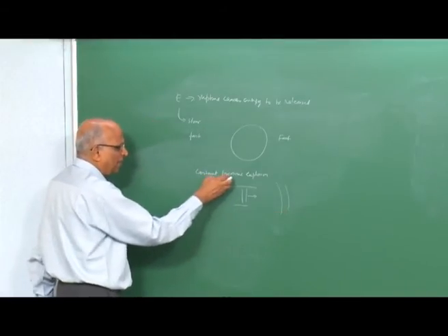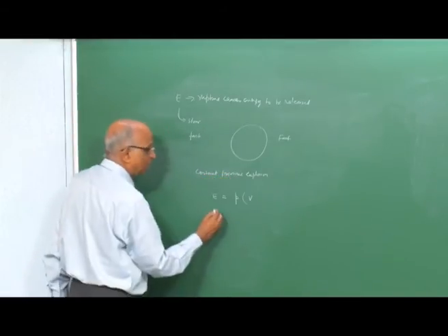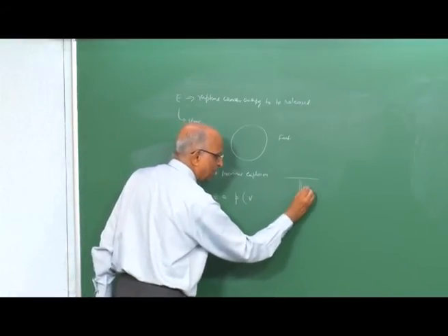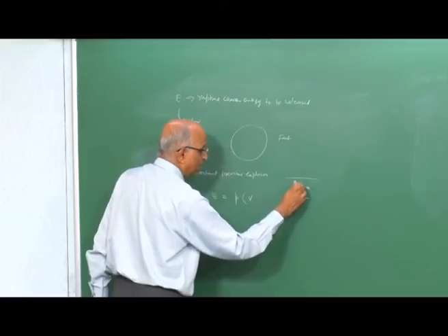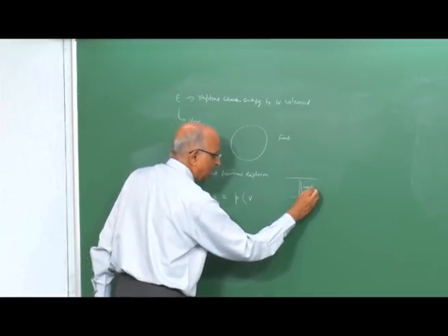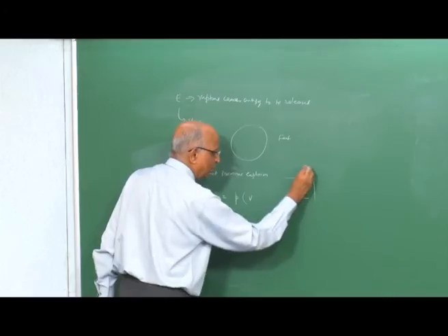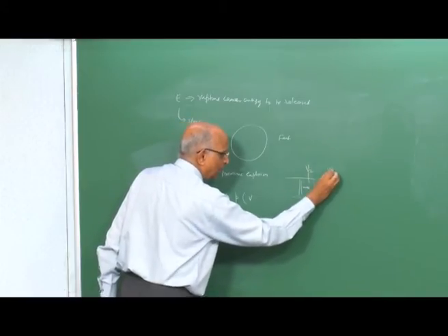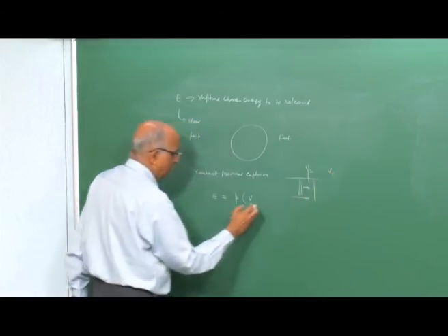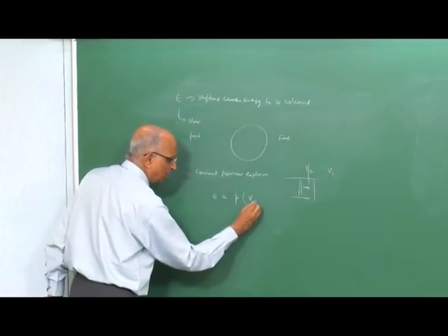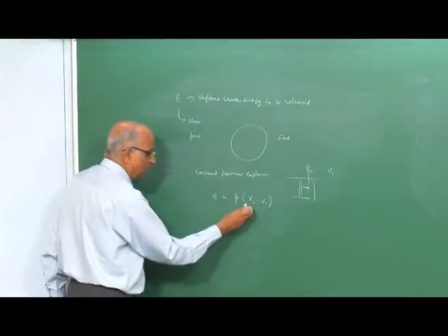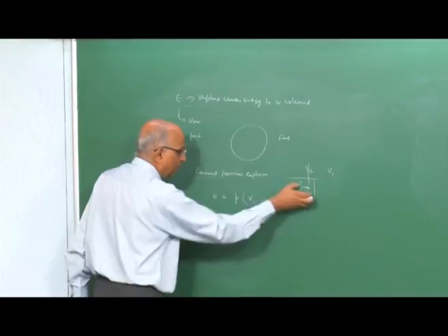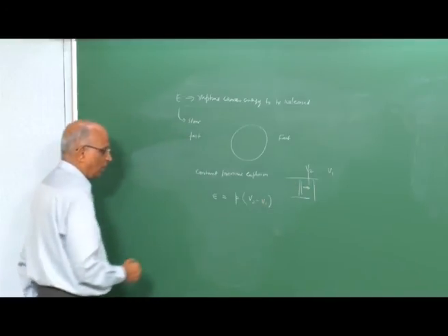And what is the value of the energy release? Let's say I have a piston pushing the gases at constant pressure, and there is no change in the pressure of the gases. Let's say that the initial volume is V2 and the final volume is V1. That means constant pressure P into V2 minus V1 is the work done, which is the energy of the constant pressure process.